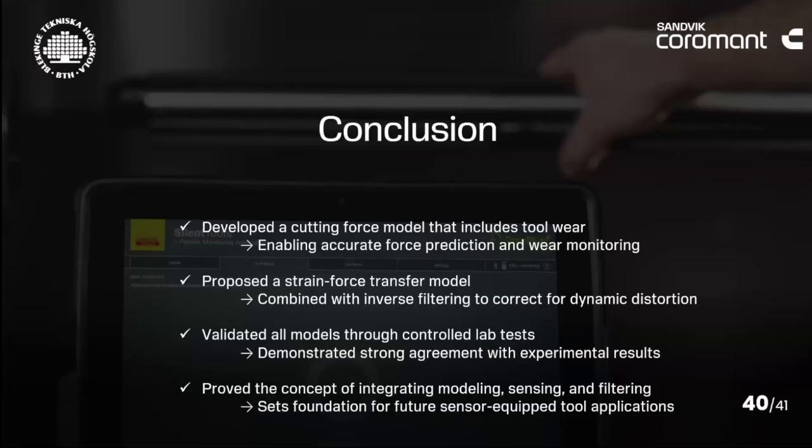To conclude, this project explores how we can combine the sensorized cutting tool and analytical modeling and signal processing techniques to improve accuracy in the machining environment. So we developed a cutting force model that includes the tool wear, enabling accurate force estimation and real-time monitoring of the tool wear.